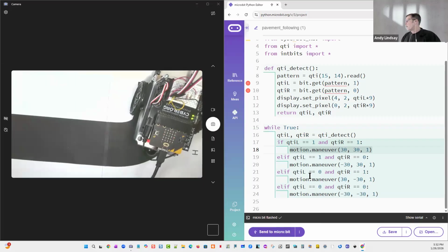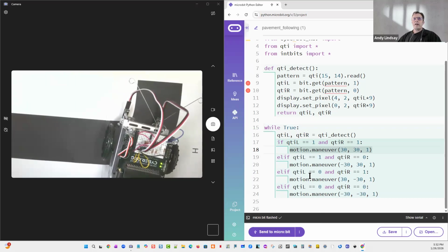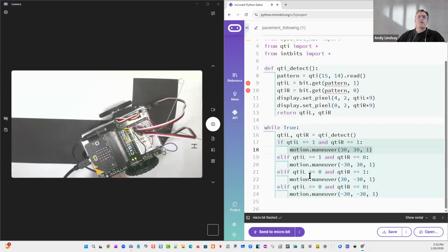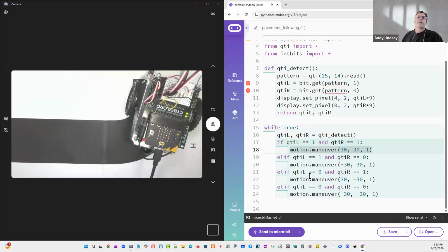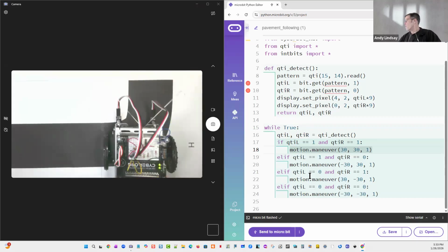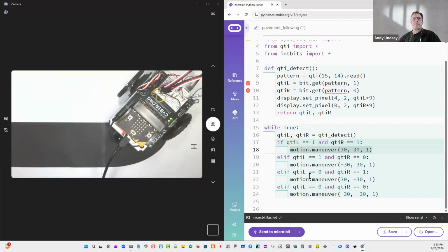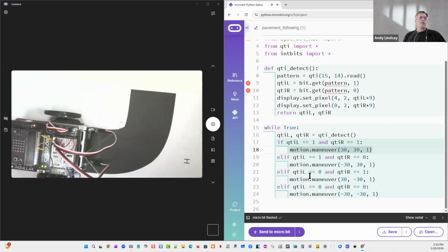Students in my robotics class end up getting an obstacle that the whiskers bump into, and then the bot has to back up and make a semicircle and then resume the course. And then also they have to follow the course to the garage and then have it park in the dark by using that break statement in the loop when the voltage is just so with this photo transistor. So again, here we are following the track.